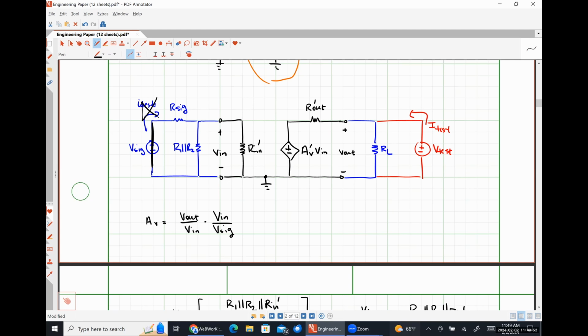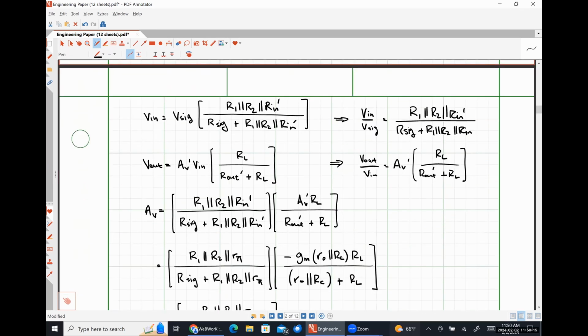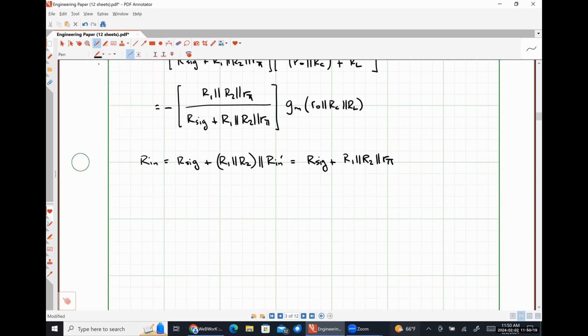So I hope that it's fairly obvious that with V sig as zero, our input voltage here is also zero. So we have no excitation on the left-hand side of the circuit. So what does this Av Vπ right here look like? A short circuit, which means we're going to see RL in parallel with RL prime. There we go. We fully characterize this much larger, more difficult amplifier just by using simple circuit analysis.